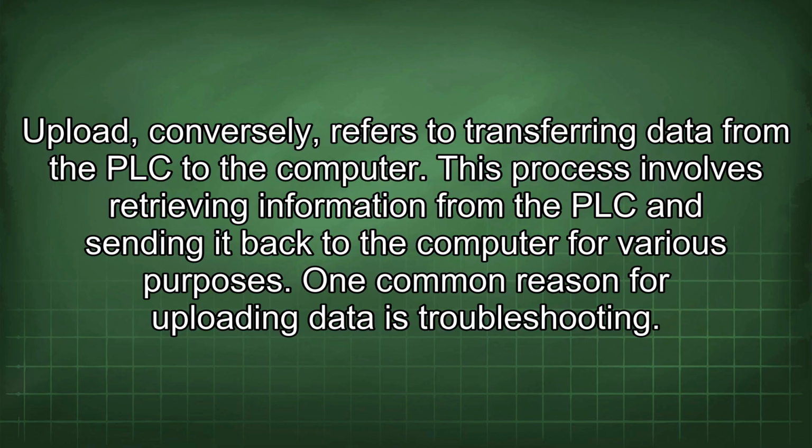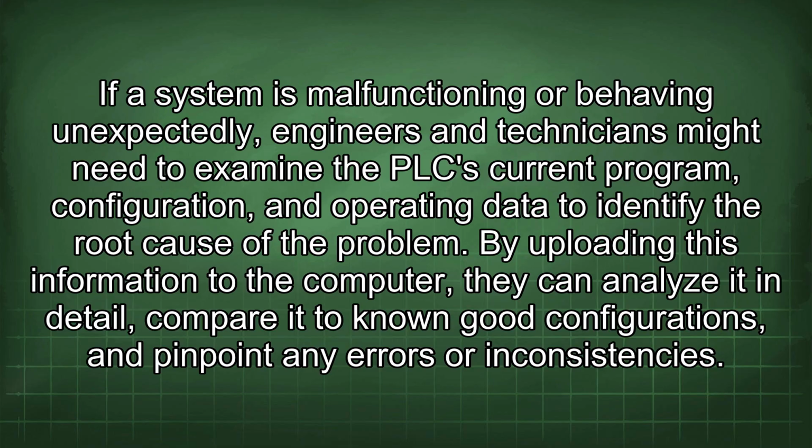One common reason for uploading data is troubleshooting. If a system is malfunctioning or behaving unexpectedly, engineers and technicians might need to examine the PLC current program, configuration, and operating data to identify the root cause of the problem. By uploading this information to the computer, they can analyze it in detail, compare it to known good configurations, and pinpoint any errors or inconsistencies.